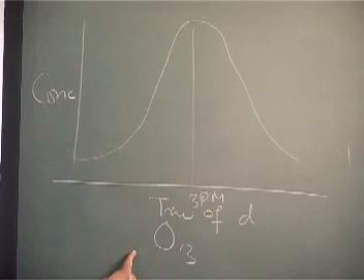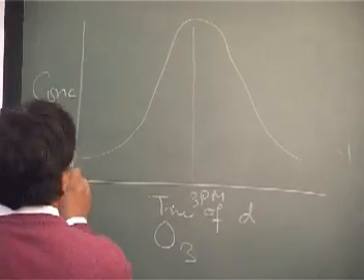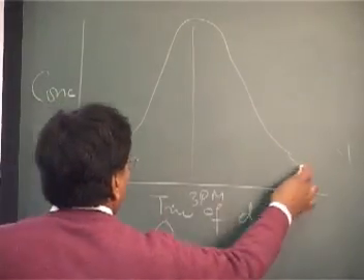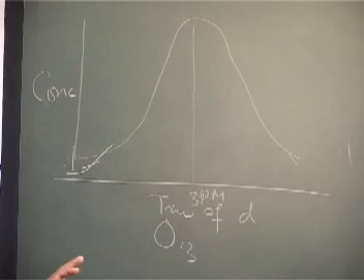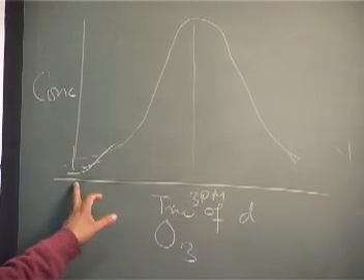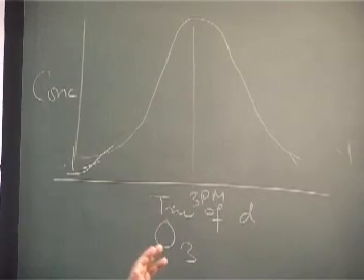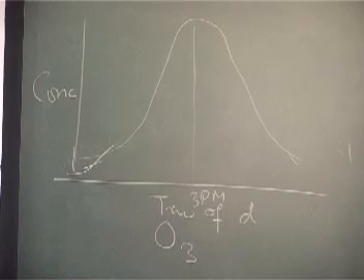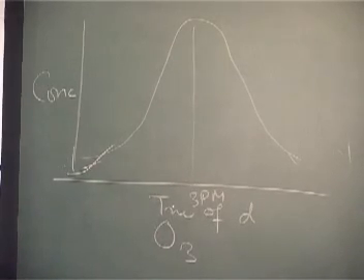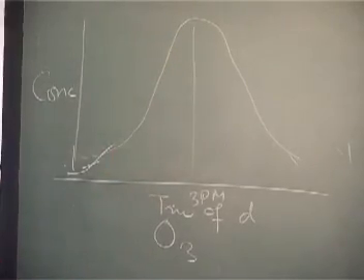If I give a standard of 24 hours, the average of 24 hours will be very low, because this is like a peak for a certain period. The point I am trying to make is, if you give the standard as a 24-hour average, the actual concentration observed in the field will be very low. And they say, well, everything is fine, people are enjoying a healthy life, but the damage is done just during the short period of this peak concentration.